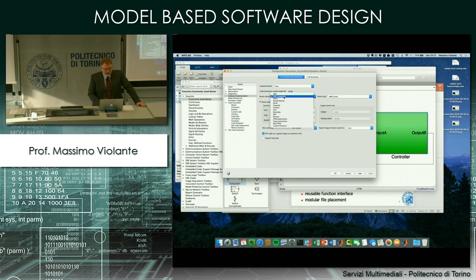That is, you can select whether you want to use an ARM-compatible processor, or an FPGA, or an Intel, or whatever else. For us, it is fine to select ARM-compatible. Then, if you want, you can also select a specific family for each manufacturer. So among the ARM-compatible, we select ARM Cortex.